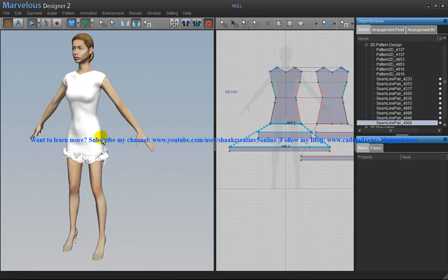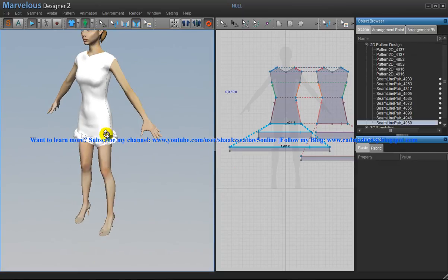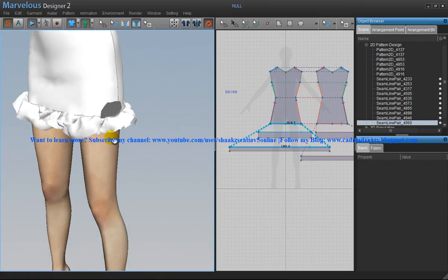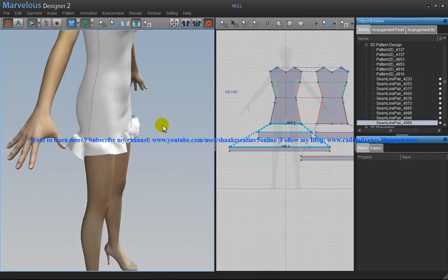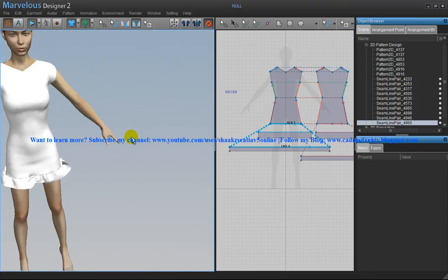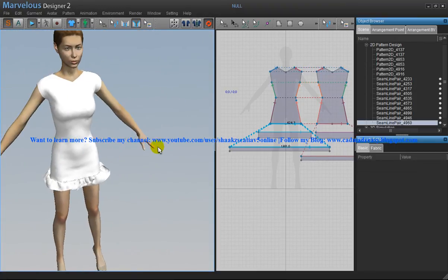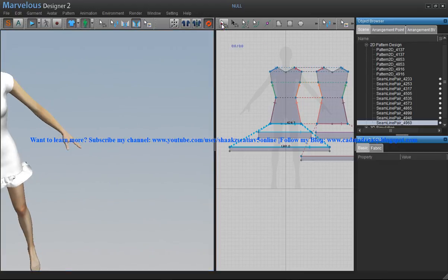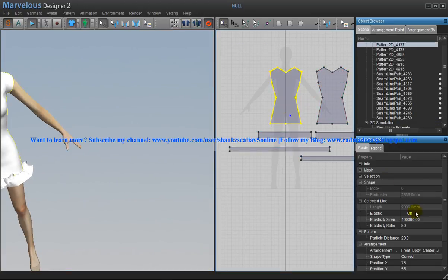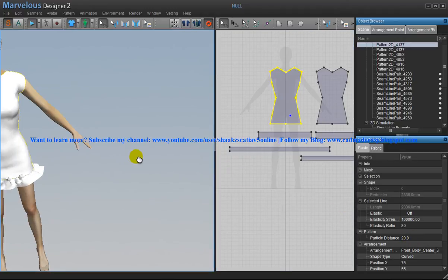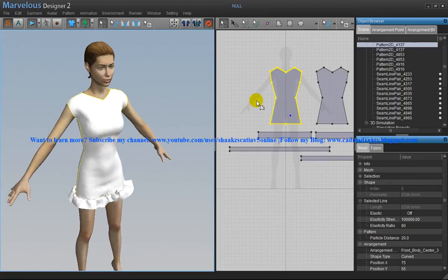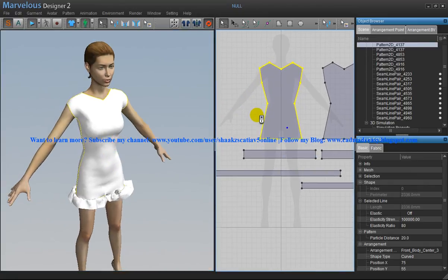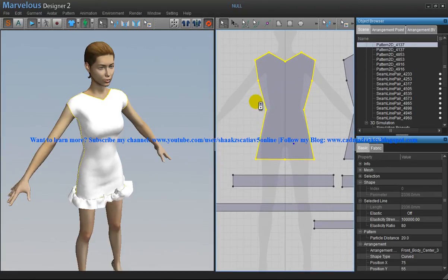and you got yet another layer of cloth over there. You can see that. As the particle distance is less, I'll talk about the particle distance now. See, when you select any of the cloth or any material, you have something called a particle distance here. When you reduce that particle distance, it's going to have a better output. Similarly, you can go for hands also.